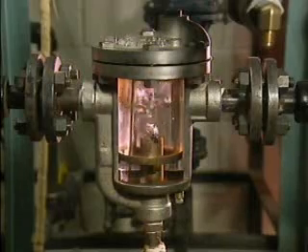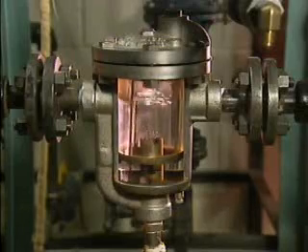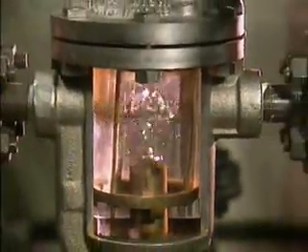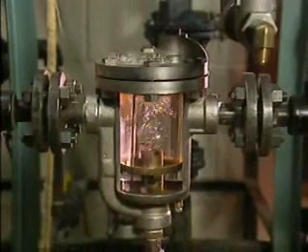Inverted bucket traps are also able to handle air and other non-condensable gases because these gases are less dense than condensate. However, the vent in the top of the bucket is small, and only a correspondingly small amount of air can pass through it. So to avoid problems, inverted bucket traps generally should not be used if large volumes of air must be removed.